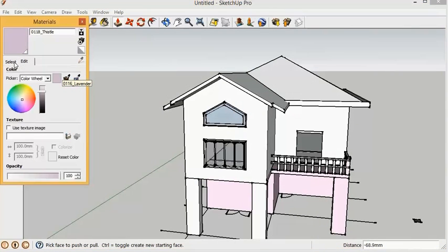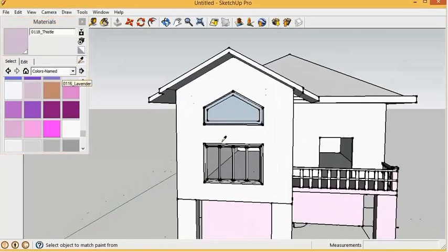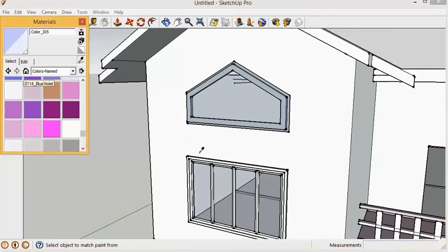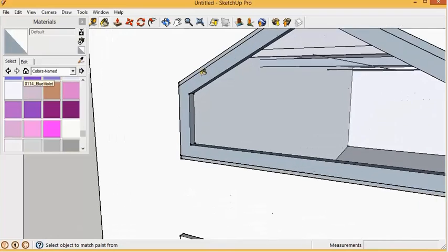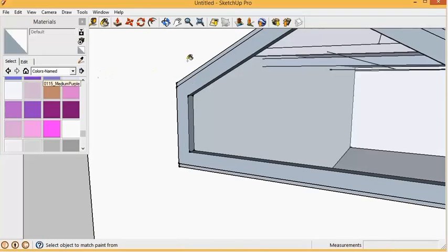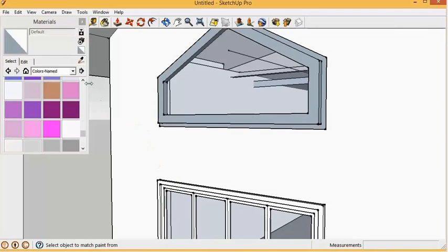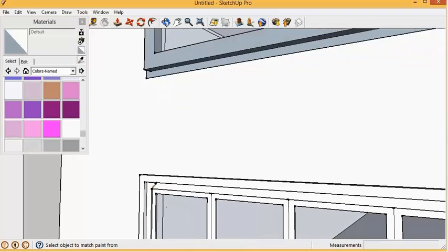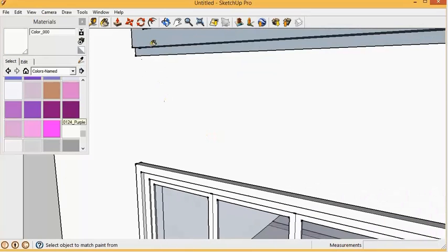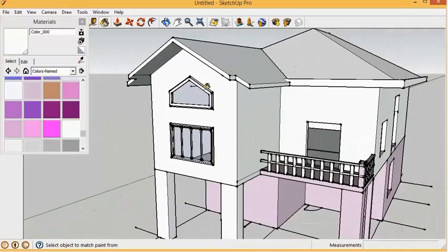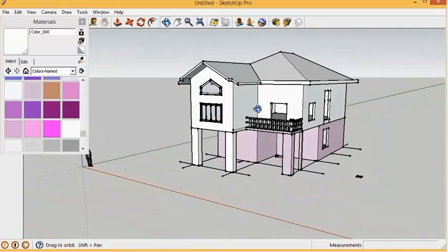So I want to measure the bottom corner of this, and you basically just left-click to set, and very similar to the rotate tool, you drag out a line, and then you rotate it up or down. Now, this will snap to 90, 60, 45, and so on, and it will also snap to whatever it's aligned to. So in this case, this edge here, and we can see here that the angle is 53.6 degrees.